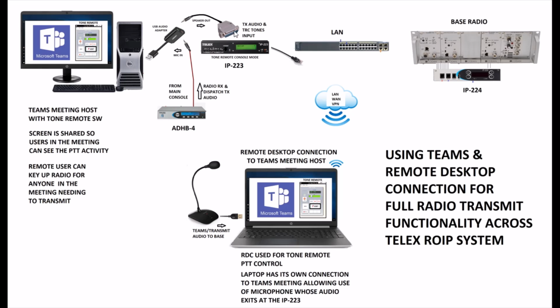And what happens is, in the tone remote console mode, it decodes those tones and converts them to radio over internet protocol packets that go over your Ethernet LAN and then get translated back into push to talk and analog audio for your base radio over here.